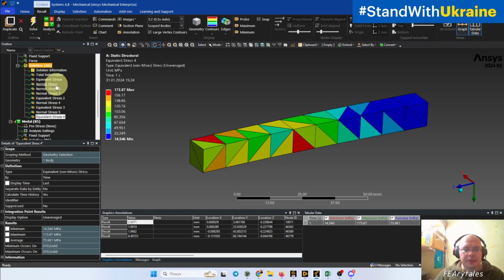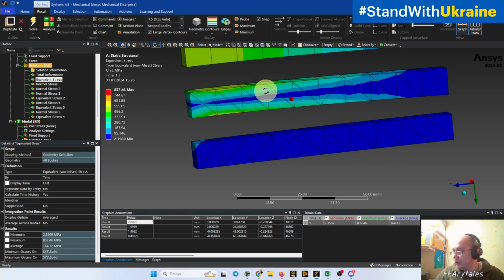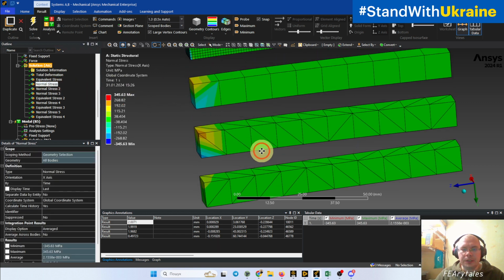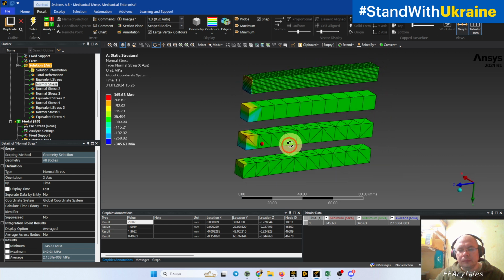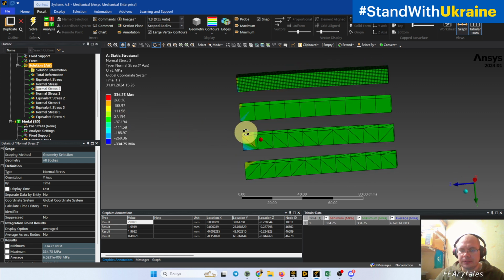Okay, let's talk not about von Mises stress, but about component stress, because they can show us whether we have a problem with the stress distribution or whether it is correct. And if we take a look into the stress distribution in the x and y directions, this and this, we can understand that it's not the real one which we need.